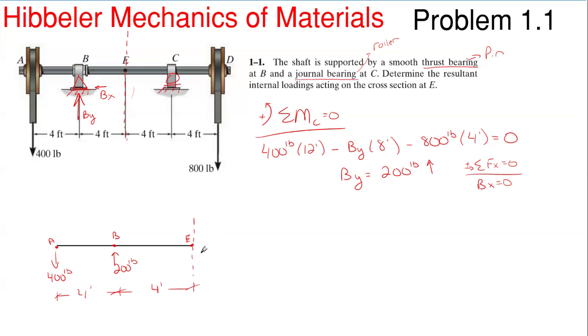So remember with internal forces, you're going to have 4 possible. You're going to have normal force or axial force, which is labeled as capital N. You're going to have shear, which is V. You're going to have moment, which is M, or you could have torsion, which is T. Now, in this particular problem, we will not have any torsion in this 2D system, because that would mean we have some kind of force being applied directly through the screen at you, off of the center line, which is not happening in this case.